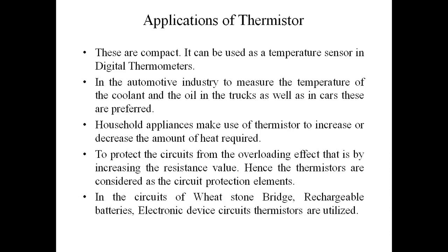Applications: these are compact. It can be used as a temperature sensor in the automotive industry, in order to measure the temperature of the coolant and the oil, in trucks as well as in cars. Household appliances make use of thermistors to increase or decrease the amount of heat required. To protect circuits from the overloading effect, the resistance value is increased. Hence, thermistors are considered circuit protection elements.